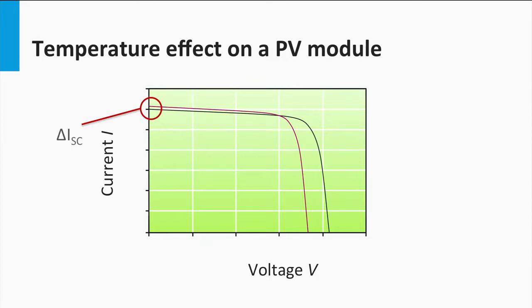The minor increase in current with temperature can be explained with the fact that carrier concentration and mobility increase in the semiconductor with temperature. This is consistent with our basic understanding that a semiconductor, unlike a regular conductor, exhibits better conductivity with increasing temperature and is a perfect insulator at absolute temperature of 0 Kelvin.